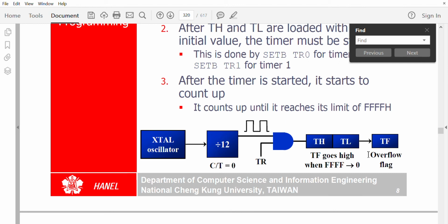So when that happens, what does it mean? It has completed the counting. So if more clock pulses come in, then you are going to the next cycle of counting. This particular counting sequence has ended and we are going to the next sequence. That particular intimation comes when there is a high to low pulse, that is FFFF to 0000, in the timer.